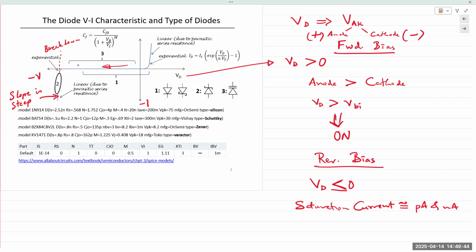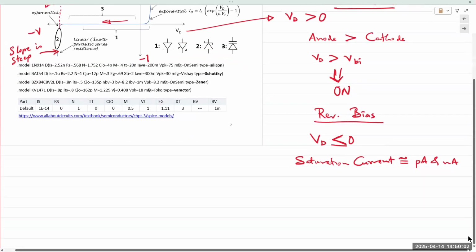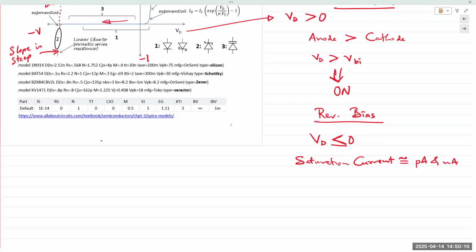So energy and power properties, power laws, and energy laws will all apply. The only way the voltage can remain constant is if the current through the diode increases, which is where this characteristic is very useful. In the reverse bias, we talked about breakdown, and I mentioned Zener, right? So breakdown occurs due to 2 different kinds of mechanisms.